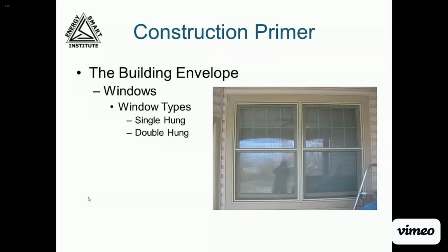move, and many times the two sashes will tilt in for easy cleaning. These windows generally have a window lock at the top of the lower sash. These locks provide security, but they also pull the upper and lower sash tighter together to help prevent infiltration between the two sashes and around the frame as the window is pulled tightly closed when it's locked.